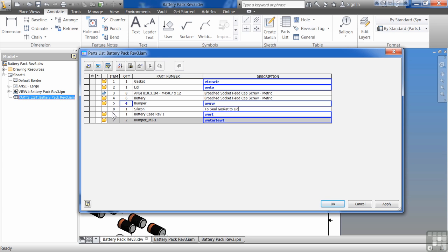So once you do that, you can say renumber over here. And you can see what happens is that changes the item number here for the case to number 7. I can actually save that back to my bill of materials. So now number 7 is number 7 in the bill of materials, and it's going to override this mirrored part.